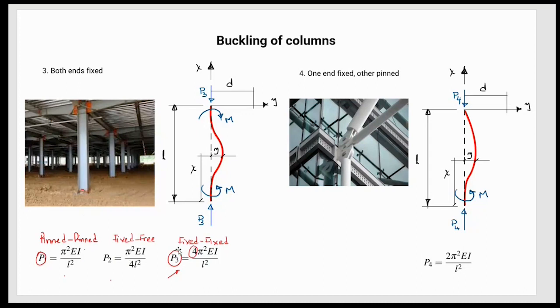It's in your hands to select how you would like to handle these cases, knowing that if you choose a fixed condition, the buckling strength is going to be larger than in the fixed-free condition. That's simple yet powerful, because it is in our hands to decide this kind of thing.